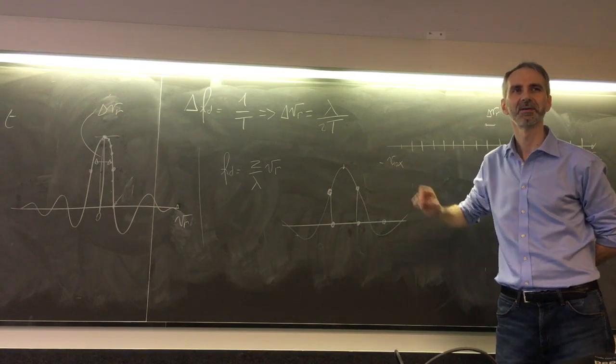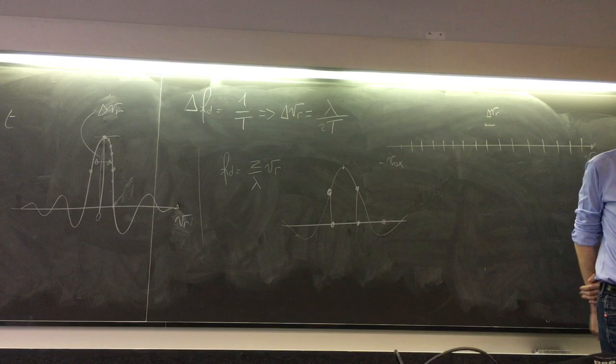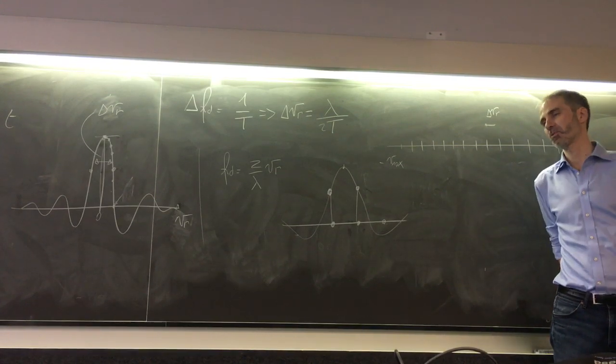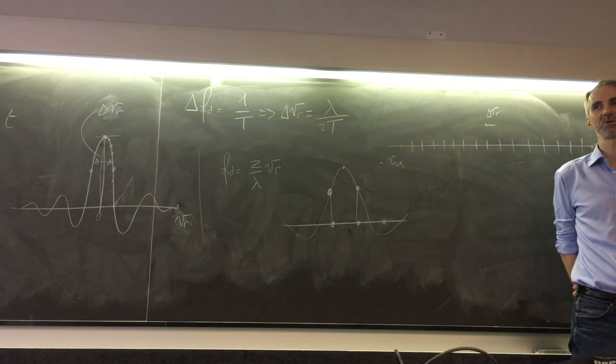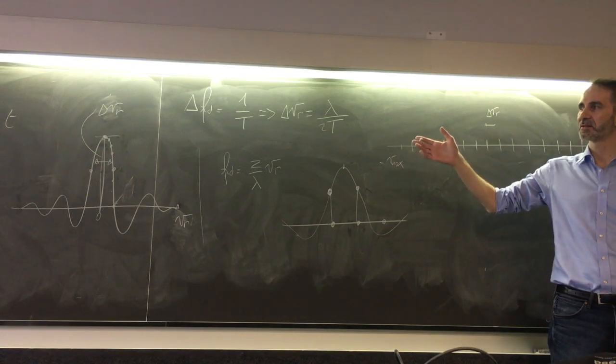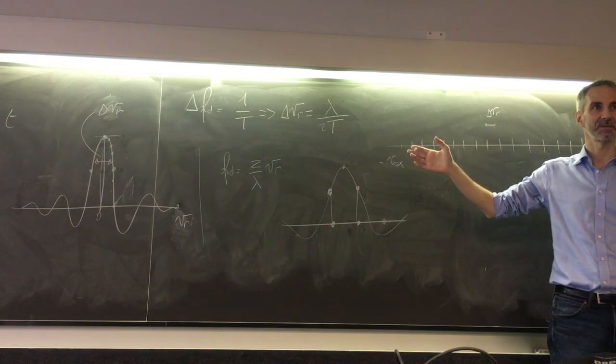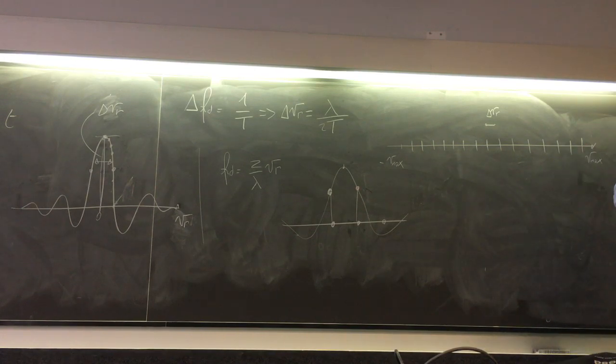Yeah, but the point is that by saying sampling, that means that we are trying different Doppler frequencies. Yes, of course. That's the point. Absolutely. You have to decide a priori which Doppler frequencies you are testing. So I would suggest to have more, yes, within a certain limit. Yes, of course. But this is not done in hardware. This is done in software. So you have to sample your function.